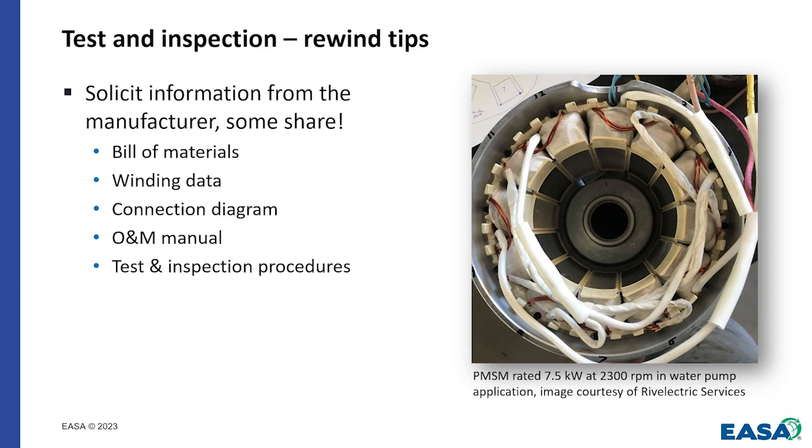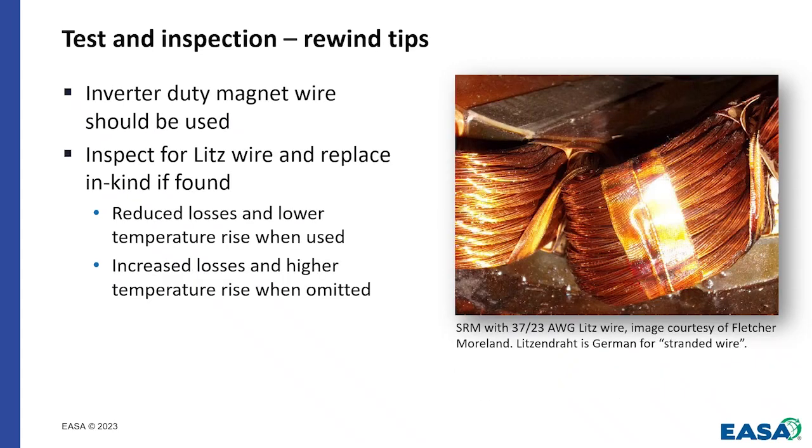Now this is one area that can get us into trouble, especially with delivery time. You need to inspect these coils very carefully because these are all inverter-driven machines, and they operate at fairly high frequencies, and sometimes the number of turns per coil is going to be a pretty low number, which means the turn itself is going to be pretty big. And if you do a lot of large form-wound coils like generator coils, you'll see that the laminating of those turns, even at power frequency, is done to reduce eddy current losses and circulating current losses that you can experience.